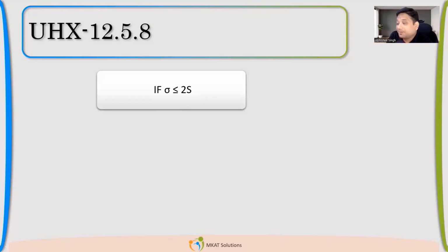If you know the different types of stresses, the reason lies in that I can permit more stress for the bending type. Here there is bending stress, and bending stress will not directly result in failure, because for the bending moment across the section, one side is plus, the other side is minus, so overall it's nil. That is the reason it does not result in failure.